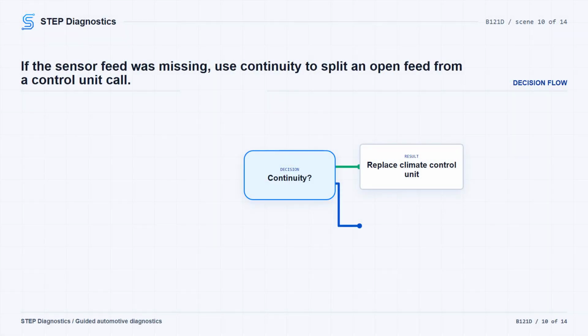If the earlier voltage check failed, turn the vehicle OFF, disconnect the climate control unit 32P connector, and check continuity from climate control unit connector No. 17 to humidity/in-car temperature sensor connector No. 1. If continuity is present, replace the climate control unit. If continuity is not present, repair the open in the wire between the climate control unit and the humidity/in-car temperature sensor.